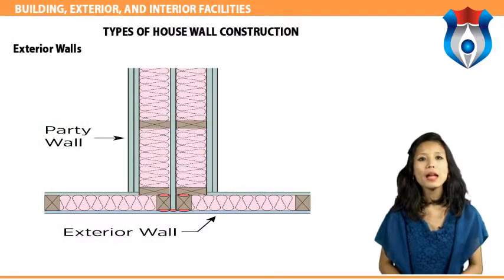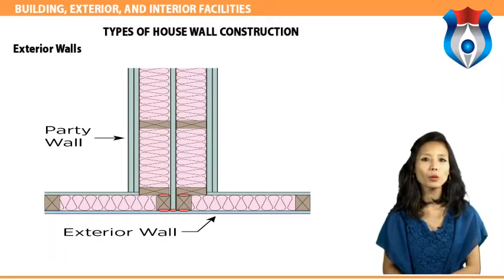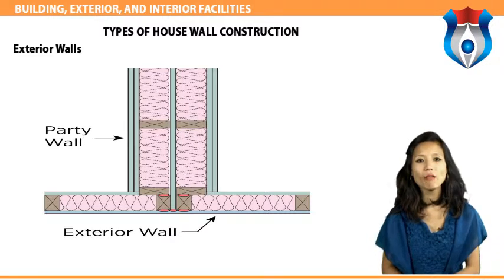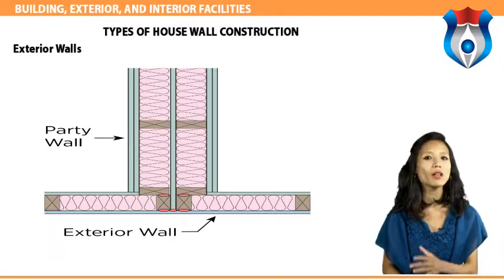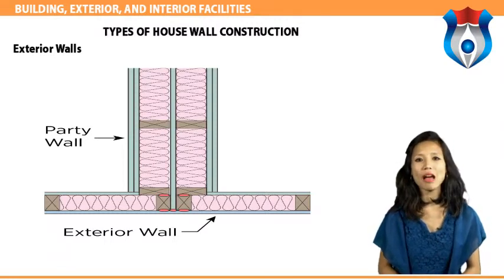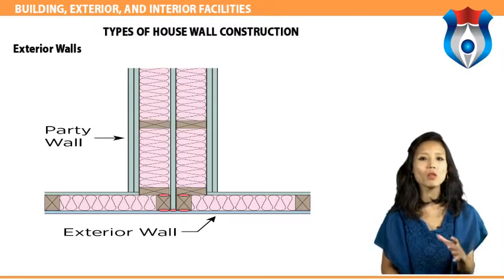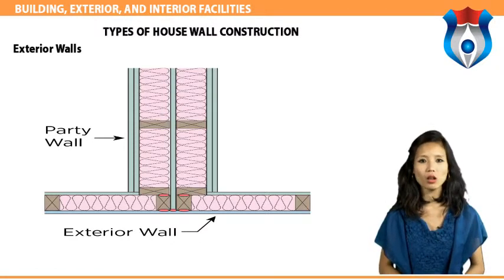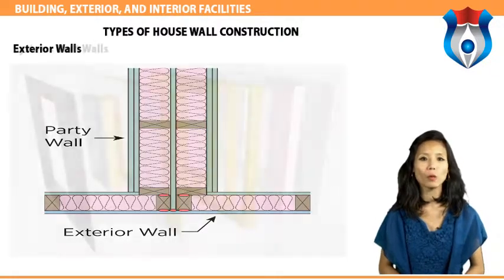Exterior walls. Exterior walls shape and define the envelope of a home or building. The walls can be made of structural insulating sheathing panels, oriented strand board or plywood attached to the exterior studs and then covered with a polymer house wrap material or an asphalt treated building paper. Exterior walls have a cavity opening which includes insulation materials to protect the home from weather penetration. After the house wrap or building paper is attached, the surface is clad with the material visible from outdoors such as brick, wood siding or stucco.